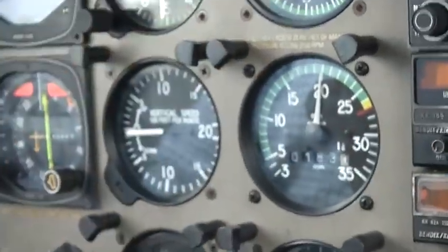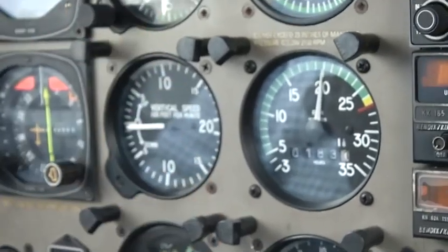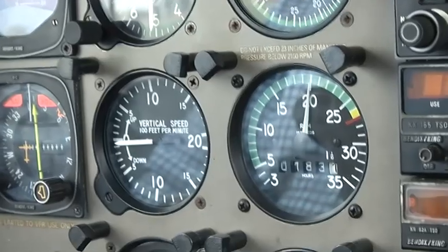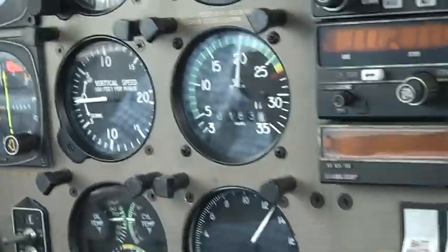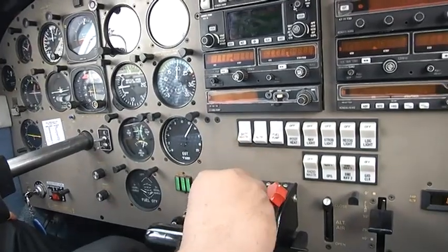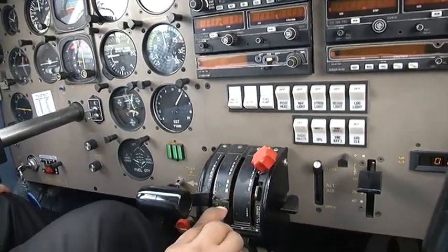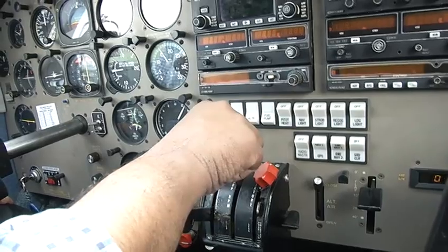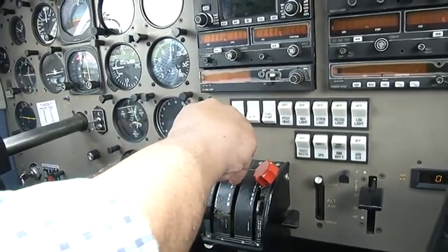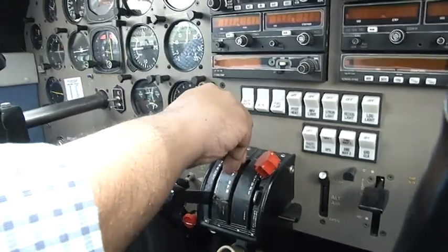The check what we have to do at the moment is we need to observe that the drop should not be more than 500. So just now watch out. I am moving this lever to the coarse pitch. See, this lever has gone to the coarse pitch. And you can see, you have listened to the variation in the propeller.